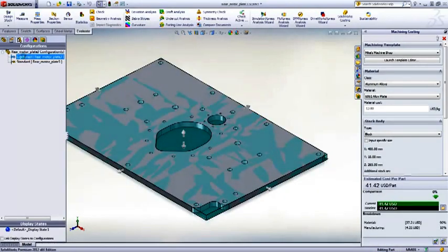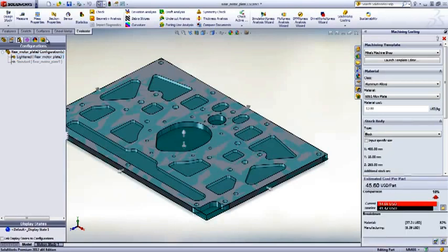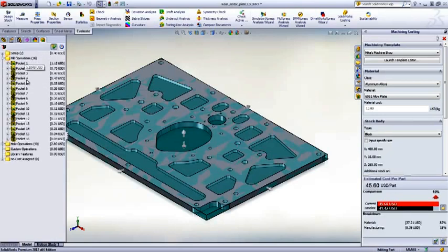In this part, we want to evaluate the cost of reducing weight by machining additional pockets. Costing re-evaluates the manufacturing operations based on the required tool size, type, and cutting speed to remove the necessary material. The new costing tool in SolidWorks 2012 is a great asset for saving time